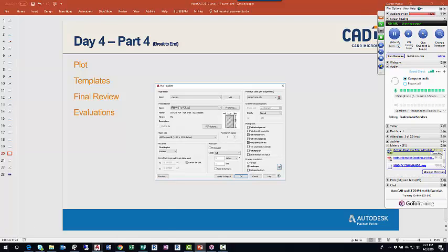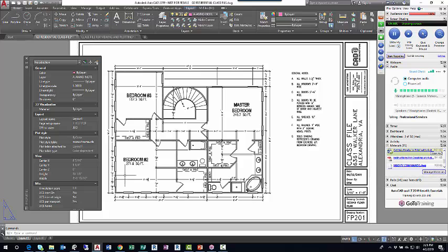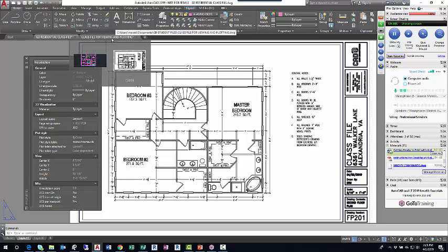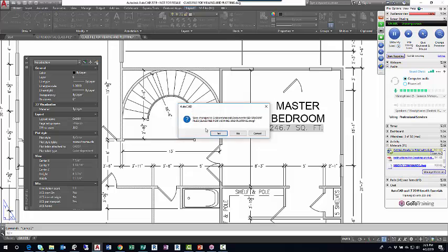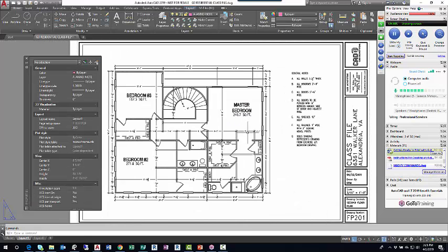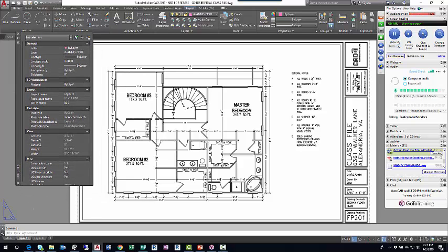Once you've gotten your drawing to the point where we have it, I'm going to get rid of my class file for viewing and plotting. That's served its purpose for me. Here's the drawing that I've been working on, GD residential class file, and I'm going to rename the layout tab. The layout tab currently is layout 1. We're going to output this to PDF, and when you output to PDF, the PDF will name itself after the drawing file and after the layout tab, right?